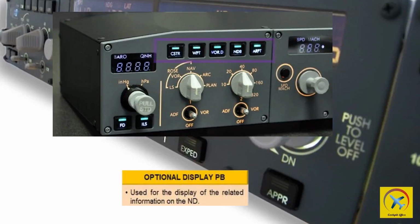When the non-directional beacon button is selected on, the NDB symbol is displayed a magenta color. When the NDB symbol is part of the flight plan, the symbol is a green color. The NDB symbol is a white color if the to waypoint and blue when tuned by the FMGC, automatically or manually.